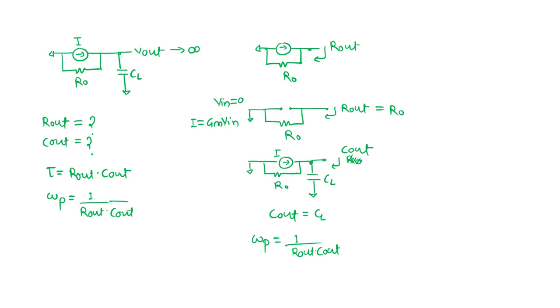So when we calculate the effective resistance, we are not worried about the capacitance at that node, and when we are calculating capacitance at that node, we are not worried about the resistance. Or we can write this also like this. When I'm only looking for my capacitance, I will not be worried about this impedance.